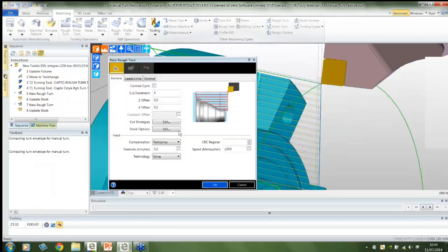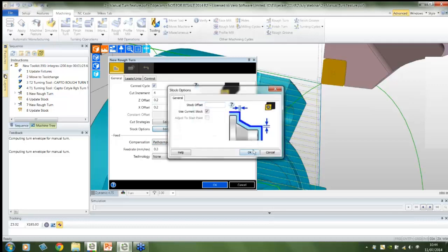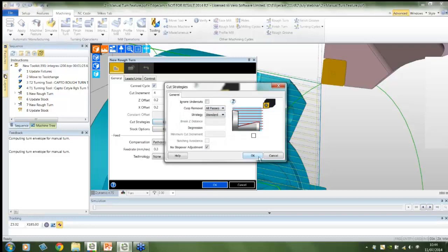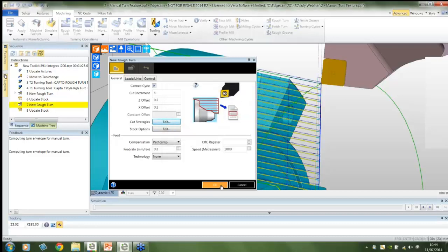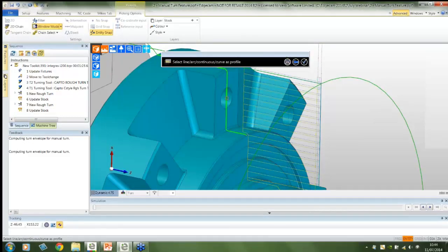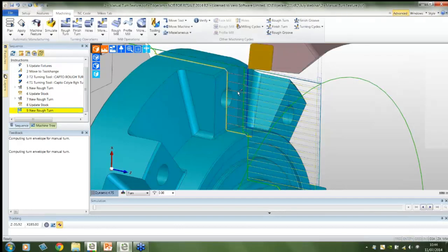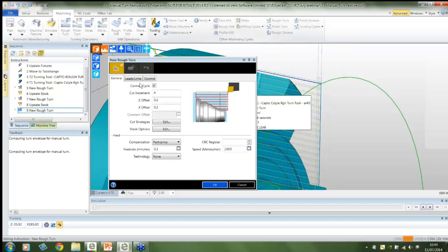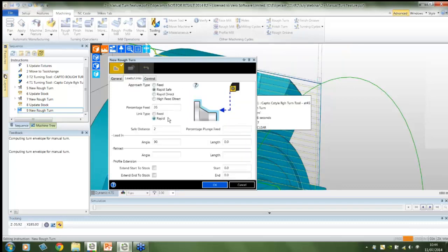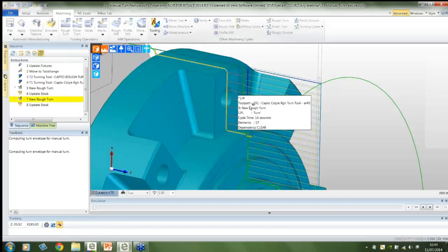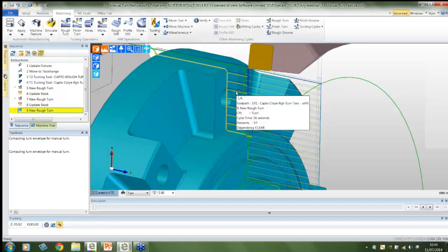Now, in respect to the rough turning cycle, I'm just going to use a turning cycle, if I can remember how to use it, Simon, and just set this up in the good old way. And I'll ask Edgecam just to select that area there. So obviously we've just got our turning cycle in there. Just check that we've got everything nicely set up. Might just use something in there just to pull it off the face, I think. Yeah, that's better. So there's my turning cycle.